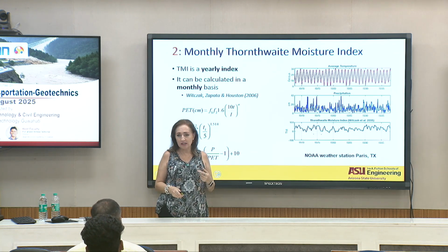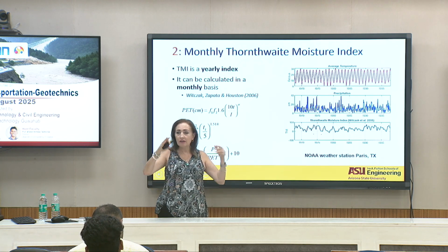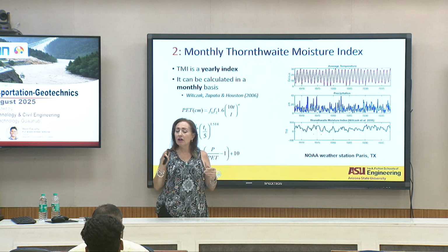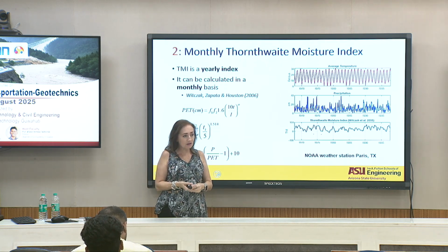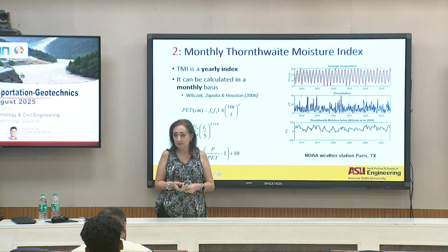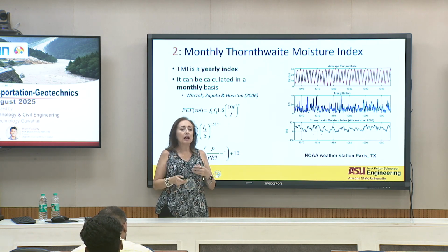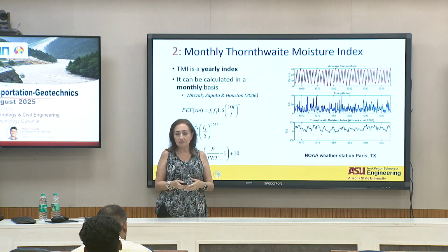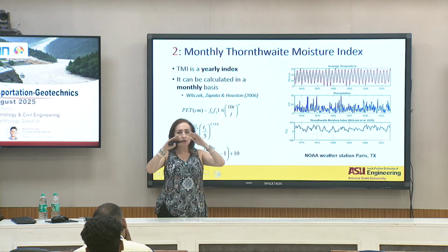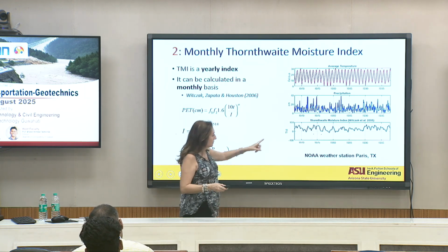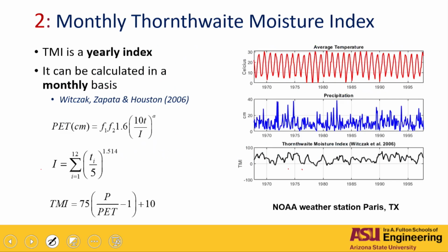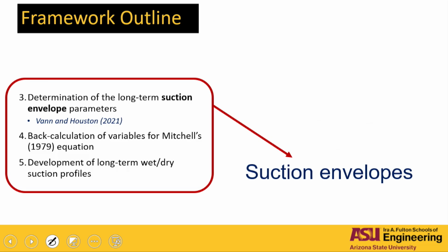But again, precipitation alone will not give you that value. We tried precipitation alone before, to see if that's the only thing that helps. No, you have to incorporate also the actual evaporation that you have from the soil. Okay, so this is how we use the Thornthwaite moisture index. It's a practical way to put a superficial value in there, and this particular point is kind of your balance point to take water or to leave water.